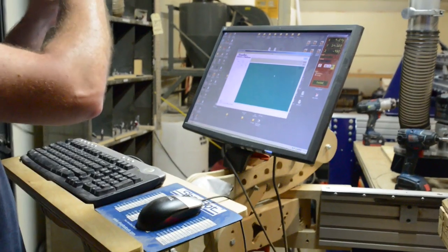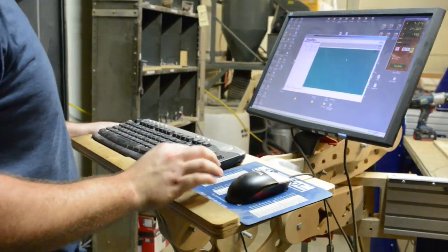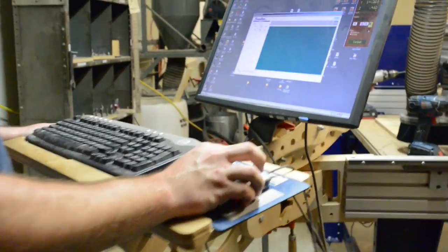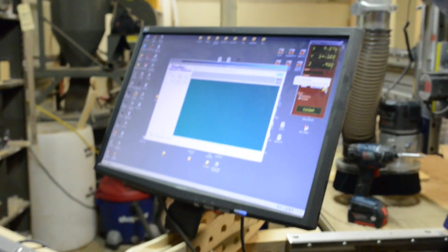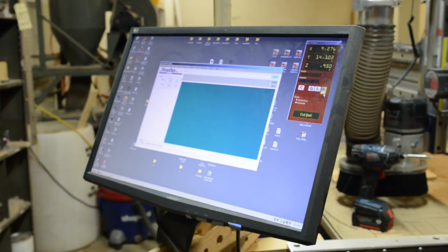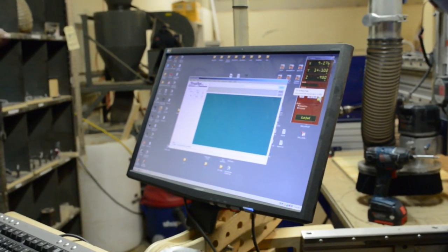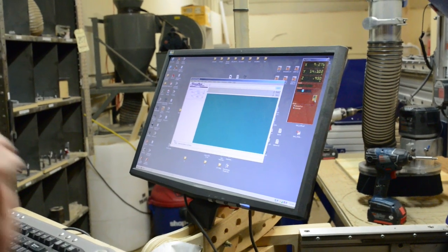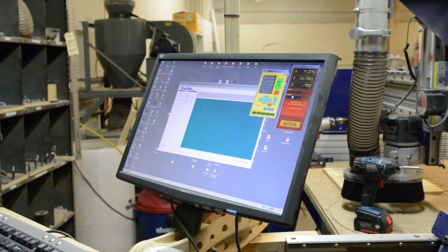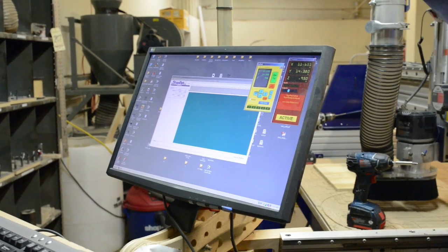So I need to manually control the gantry. I need to move it out of the way. And to do that, over here on this big control panel, there's a little yellow box, and it's the move tool. And if you read that, you can press K. Also activate it with K. So you can just click on that, and this little keypad comes up, and you can control the machine with these keypads now.